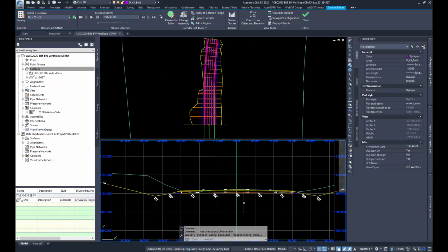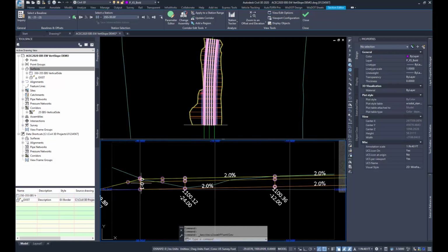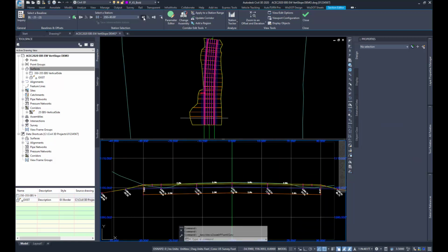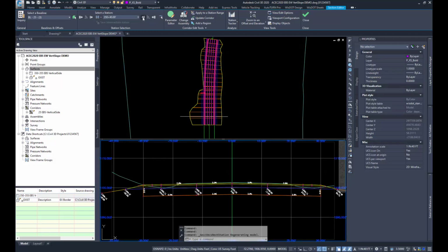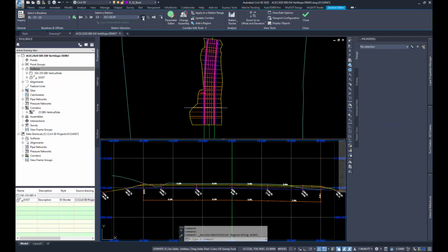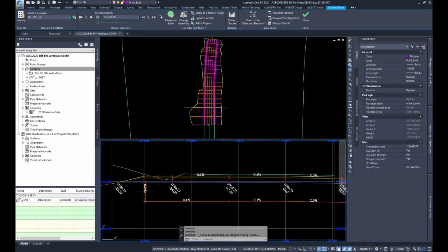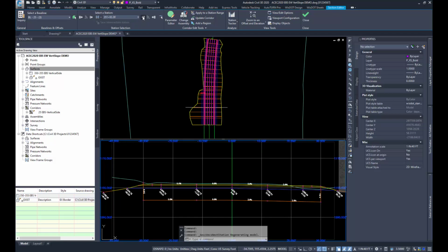Go back to the beginning here. You can see the EBS is at that 0 depth, but it is intersecting into our existing surface. As we proceed along the corridor, the depth starts to drop, following that profile. So we have the vertical surface, or near vertical surface we'll want to create, and then that'll intercept the existing surface. It does follow super elevation.